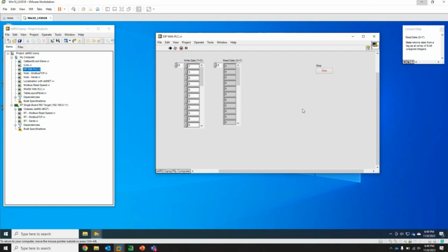But honestly, once it's working, it has been very robust. I know we've used it on plenty of products at Stratec. It's been a very robust communication between the PLC and the LabVIEW application. You're back to the same thing that you had with Modbus. You're only really exchanging numerical data. Now, granted, you can make that an array. I don't know what the limit is on EthernetIP. I know there's got to be one, but we've never come close to having to find out. String data is still going to be kind of a pain, but it always is.